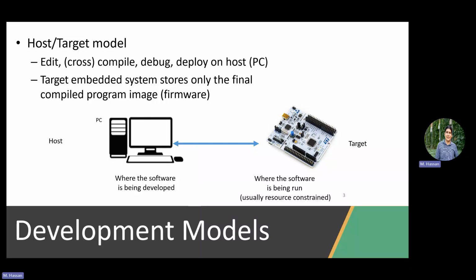Now, to enable this, your laptop is mostly an Intel machine or AMD machine, so it's an x86 ISA, right? Like in the first lecture, we talked about instruction set architecture. Your platform, well, in 241, it was a PIC, which is definitely a RISC microarchitecture. These days, it's an ARM, which is also a RISC microarchitecture. So it's a different ISA. Can I really write a program for an ISA and then target a different ISA? This is a little bit against what we said in lecture 0, that the compiler should be aware of the eventual ISA that you are targeting.